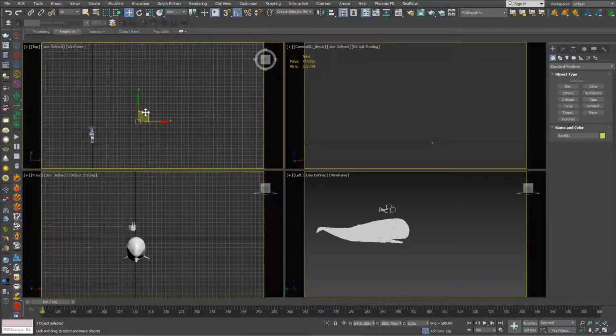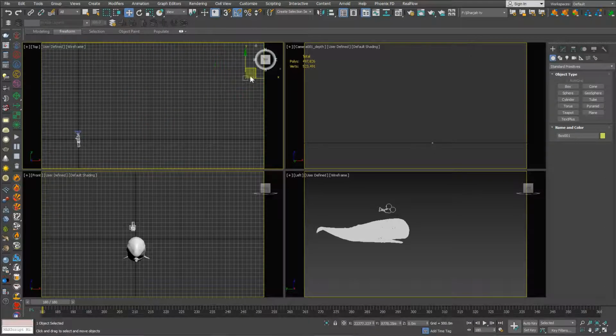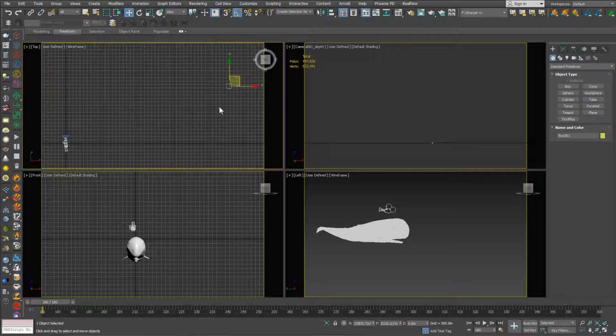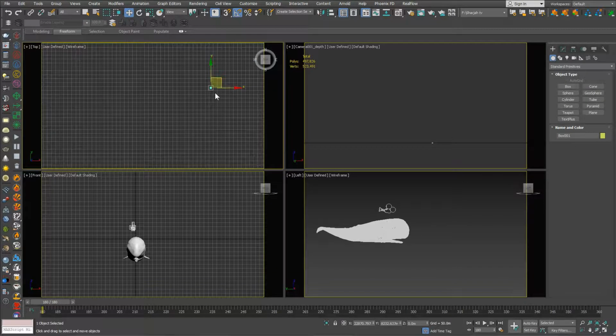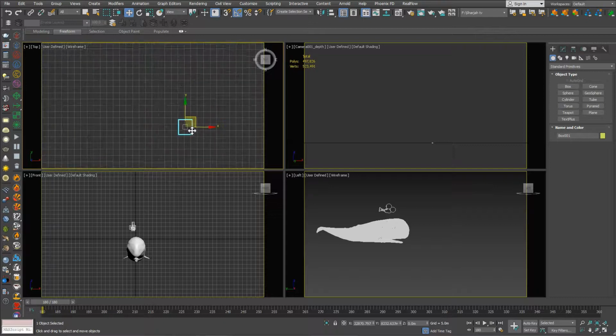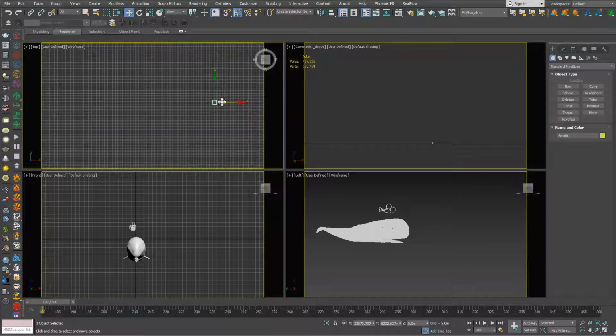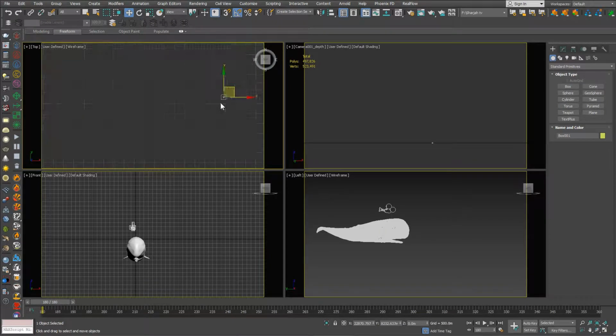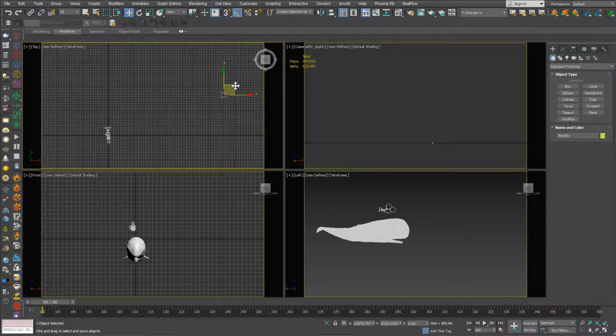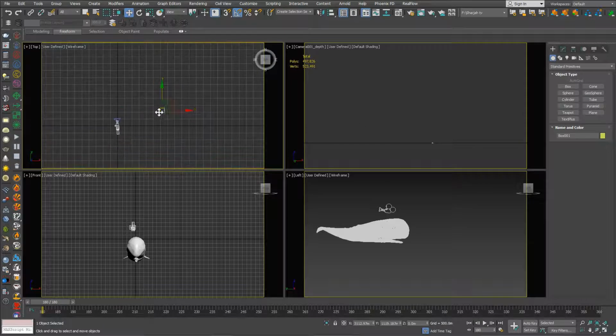And this increases when we do some simulations or another kind of camera animation even, and the camera starts shaking here, other problems will arise, based on the nature of floating point calculations and how the digital world is treating the units. So when we have a scenario like that, and our scene is big enough and all our objects are far away from the center, it's advised to bring everything here to make the area of simulation in the center, to start doing whatever we need to do.